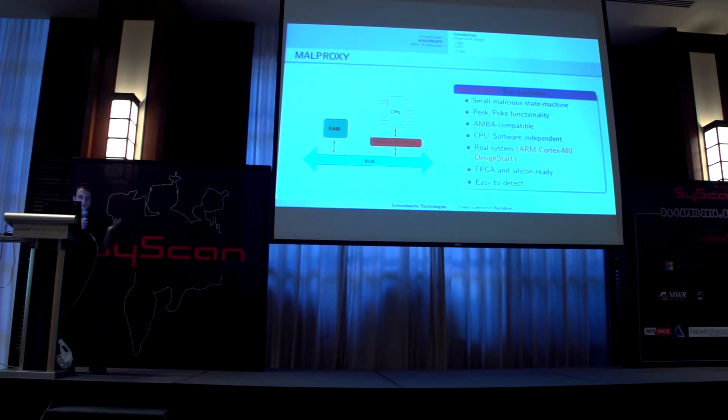With that, you basically have a debugger, a covert debugger. You can place code and read code from memory, and put every kind of code you like into memory. It isolates the CPU for a couple of clocks, so the CPU never knows what happened, and then releases control back to the CPU, but the memory has changed.